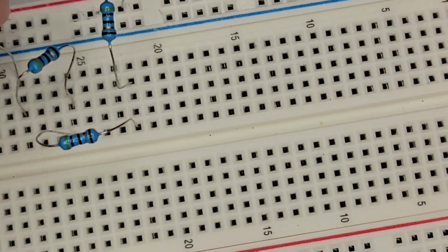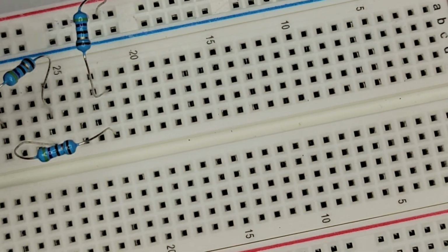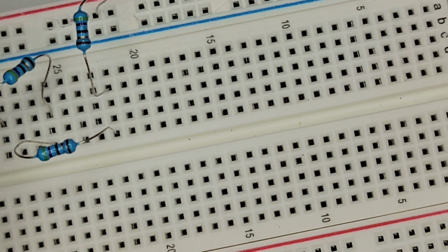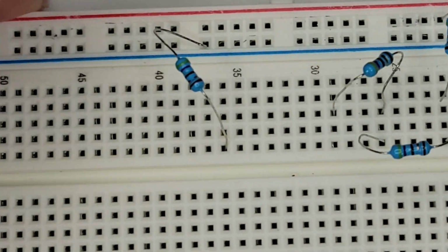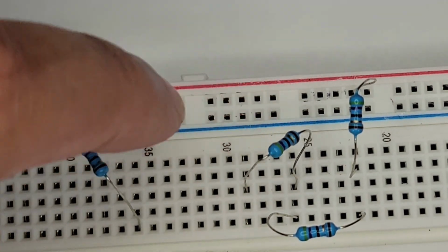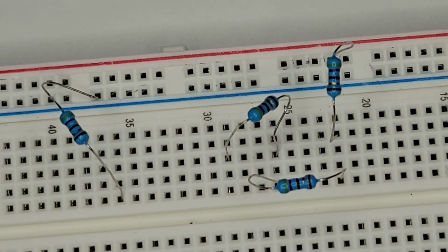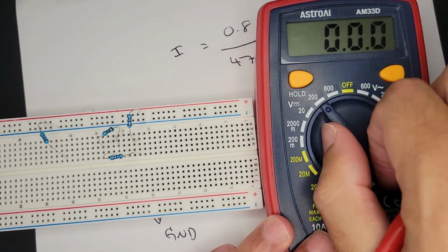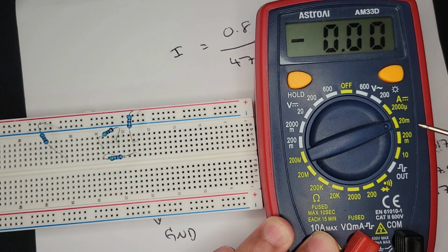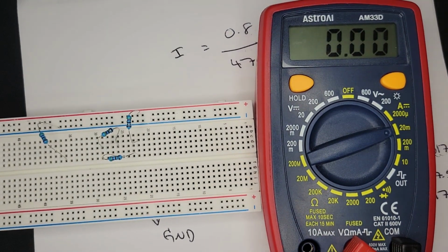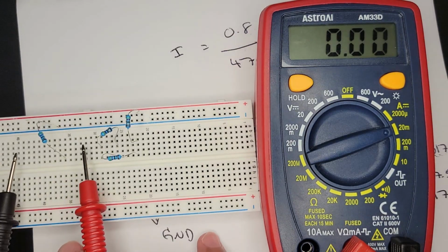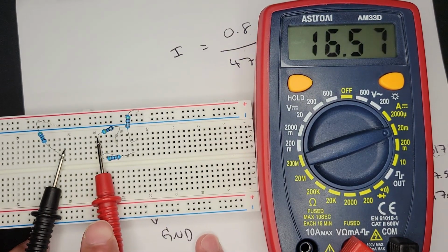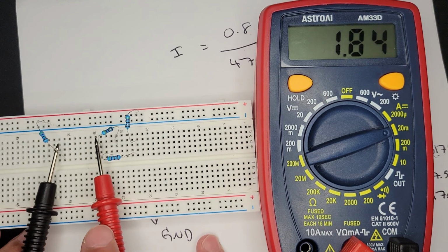So I'm going to disconnect the final resistor and put it off to the side. Sorry, you can't see it. I'll adjust the camera. So I took this one out from where it was connected to the previous one. Let me zoom out because you need to see the multimeter. So if we turn this to current into the milliamp range, 20 milliamps, and then connect these together to create that circuit, we can see 16.7 milliamps, which is close enough to 17.